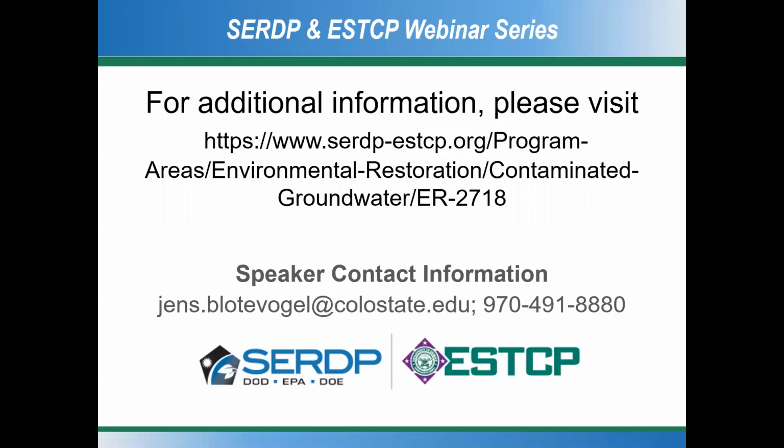I think one of the main themes of my research is to look at treatment trains and try to combine chemical oxidation with biological oxidation processes, because in general, when biology works, it outcompetes our engineering efforts. And so in certain cases, maybe also driven by the lithology of the subsurface, it may be beneficial to, say, put in a trench and homogenize groundwater flow and think about something like a reactive barrier. So yeah, again, not a silver bullet technology, but certainly something you may want to consider depending on the specific site.